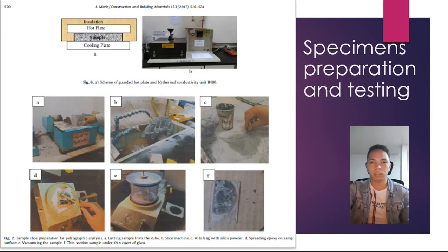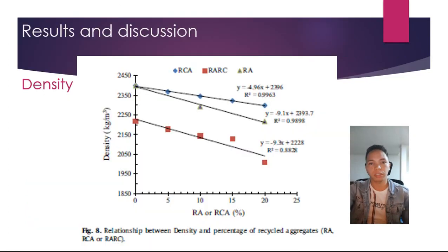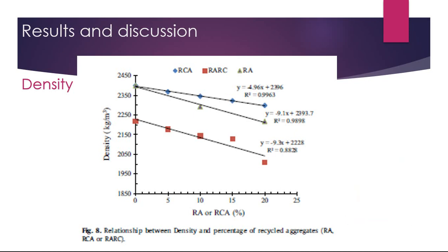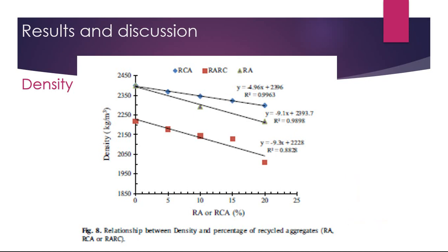The size of the particle that allows optical identification in these microscopes is not less than 0.010 mm. A sample of a slice was cut for the photographic analysis. The results were obtained. Density. Generally, the density of concrete varies depending on the aggregate density, the trapped air, the water cement ratio, and the maximum size of the aggregate. The results of mixture density are shown in Table 2.